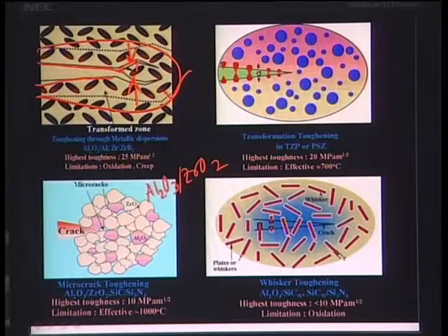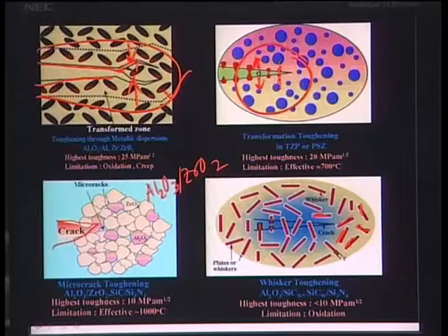You have this alumina matrix or alumina particles as well as zirconia particles, and these microcracks at the particle grain boundary cause the cracks to be stopped at a certain point. Then you have the ductile metal bridging, where under the tensile force these metals will flow, and once they start to flow, they will close the crack tip. You have the whiskers, these are the whiskers you can see. Now the small whiskers, if they are released under in vivo conditions, have a potential health risk. So that is the reason whisker reinforced composites are not used.